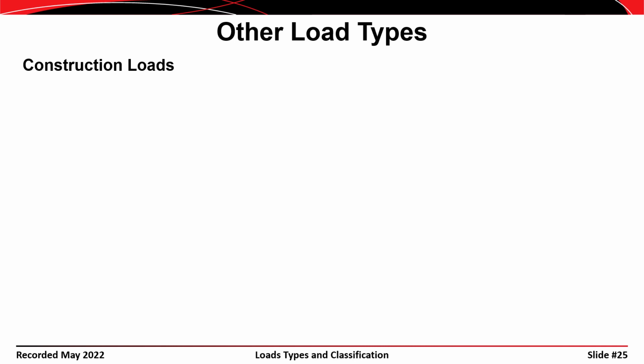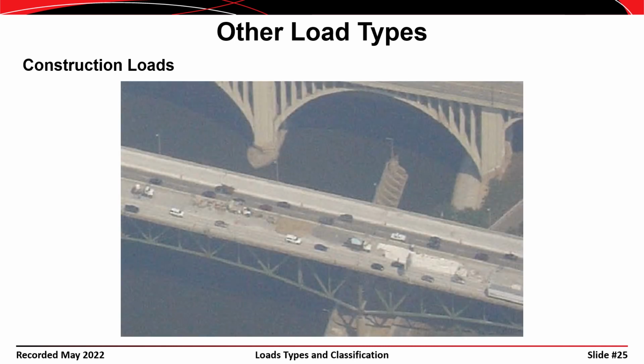And these are basically loads that are imposed on the structure while the structure is being constructed, but they aren't loads that would be expected on the building or on the structure during the service life of the structure. And I'll use as an example the I-35 bridge in Minneapolis. Now, you guys all probably know that this structure collapsed while it was under construction, under renovation.